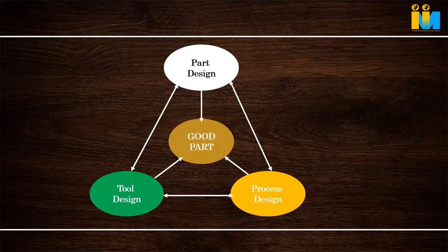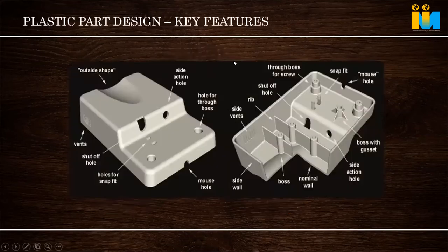At the minimum, I tell you, we should be dependent on the molding person only 5%. If it is a good tool, I make sure that within 5 shots an okay part comes. If we are molding a part and we get a good part only after 50 shots or 100 shots, that means the design or our tool is not good at all. That is an easy method to understand. If my part is coming okay from the mold in the 5th or 6th shot, it means I have done the design fine and the tooling well. That's all.